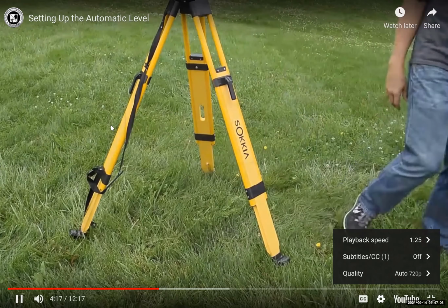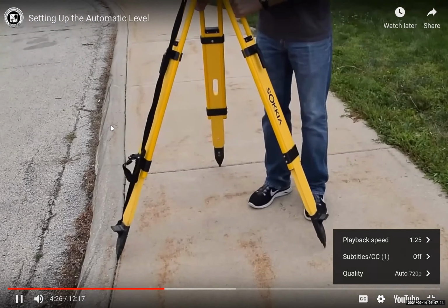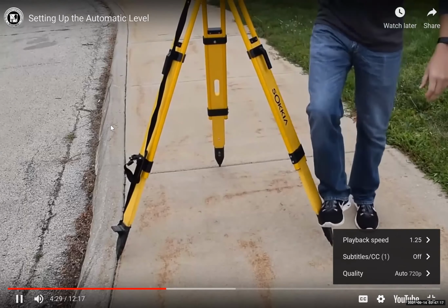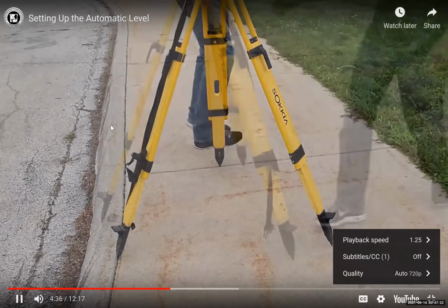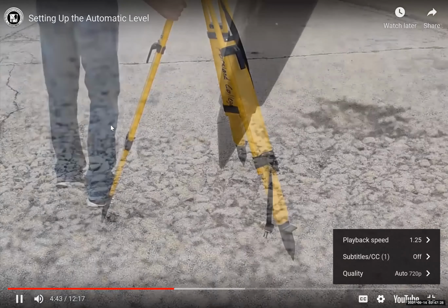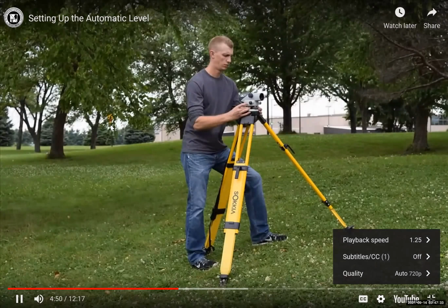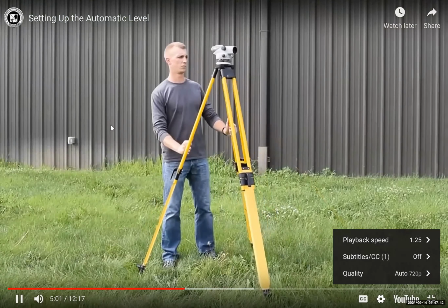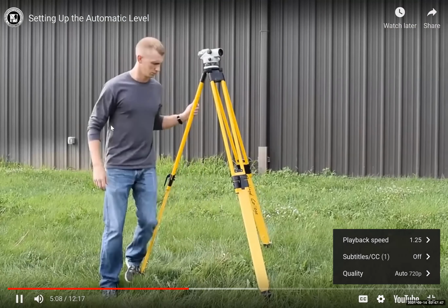On concrete surfaces, use grooves, cracks, or holes in the concrete to secure the tripod feet when possible. Even on a sidewalk like this one, your weight will help the pointed tripod tip to settle into the rough surface texture. On asphalt surfaces, you'll see the pointed tips penetrate more on hot days and less on cold days. When you must set the tripod on a hillside, set 2 of the tripod legs on the downhill side of the instrument, as you see here for stability. After planting the tripod feet, you'll be ready for the first of 2 phases of leveling. And that first phase is course leveling.